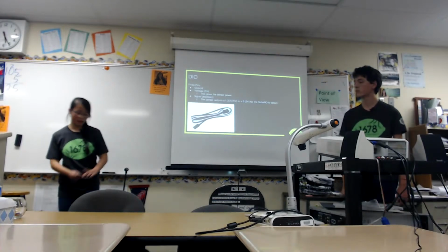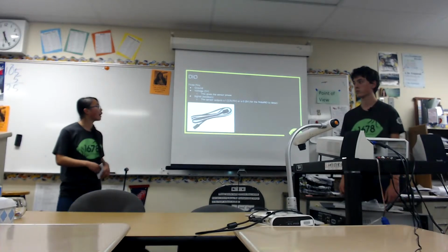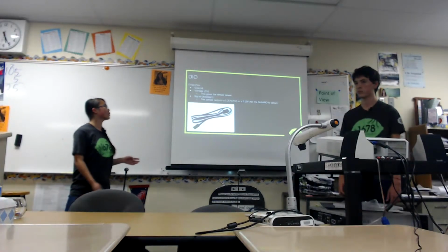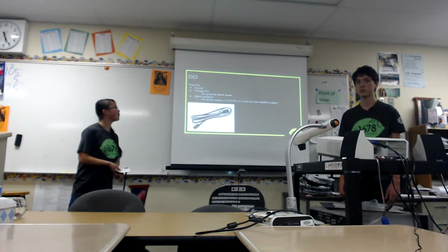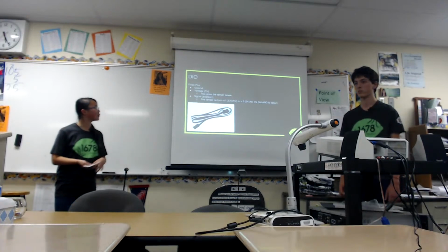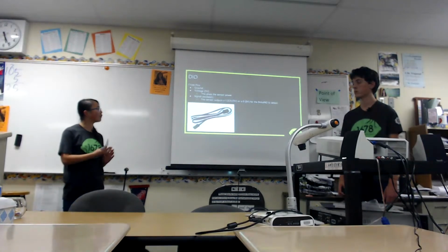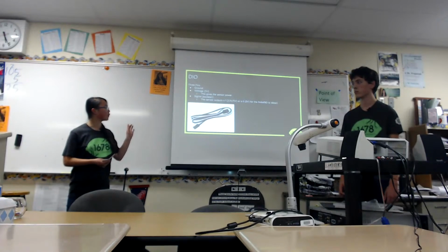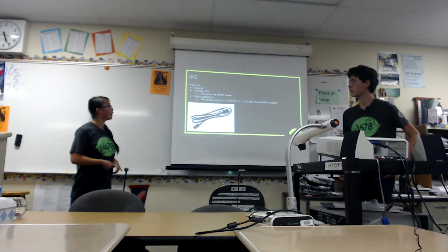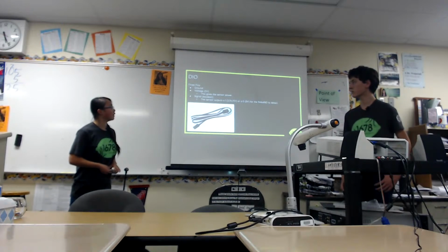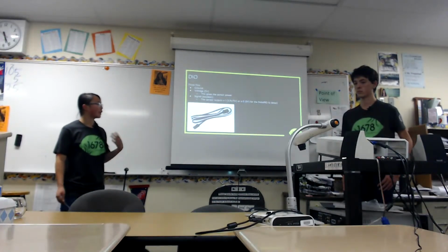So DIO is a control type, and it has 3 wires. It has power, or voltage, signal, and ground. And so this is used for sensors that have either 3.3 volt or 5 volt output. So it's just ones or zeros basically. And it is used to connect to the RoboRIO.